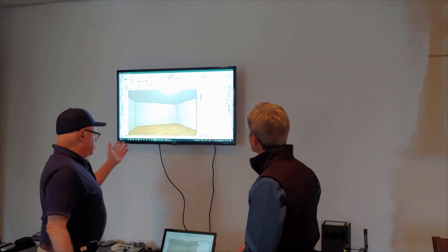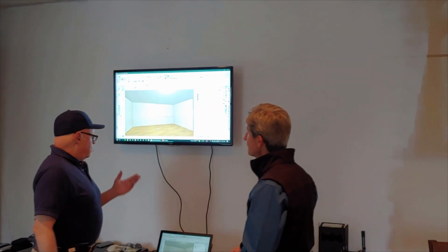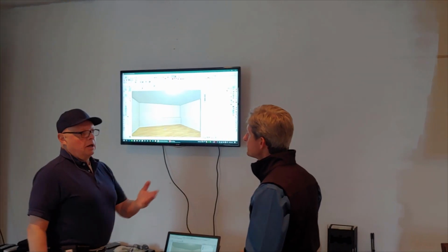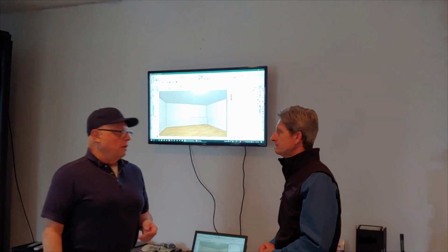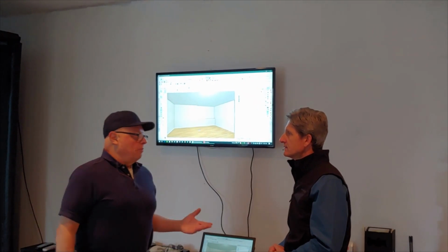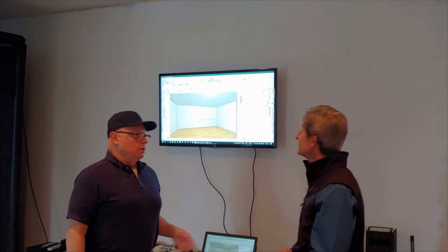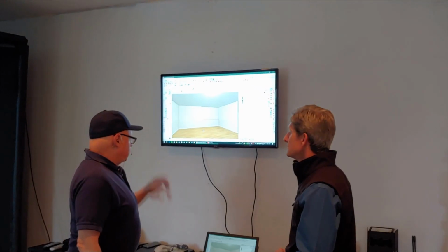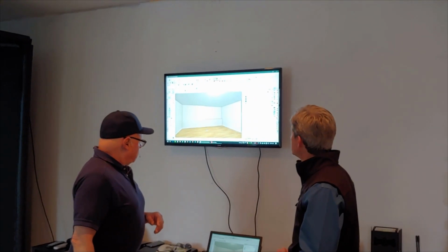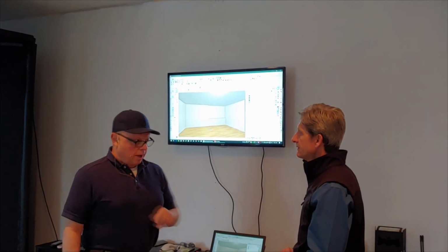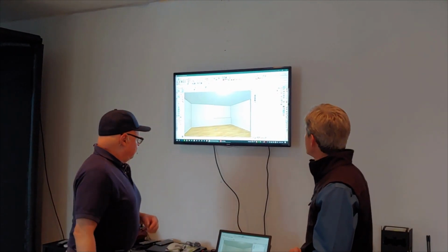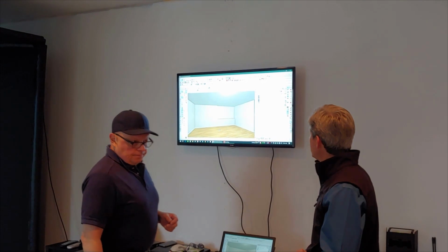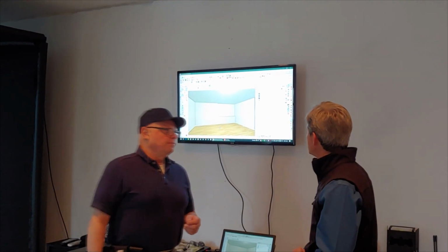Yeah. Now, there's other ways to do this, obviously. You could have just put a polyline against the wall, extruded it out, cut it, and been done. Sure. But then, if you frame the building, you have no framing. Yeah, yeah. So with this, we get the cutout that we need, and we can also put that window back there because it is a legitimate wall. Right. Okay. And then you go ahead and put the windows in, right?